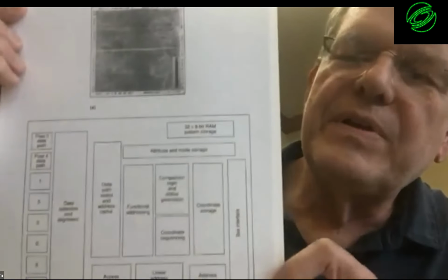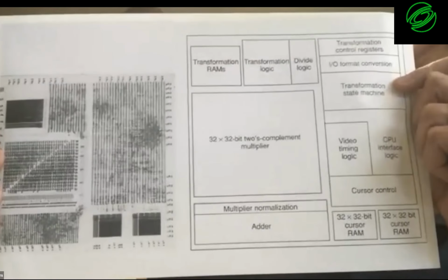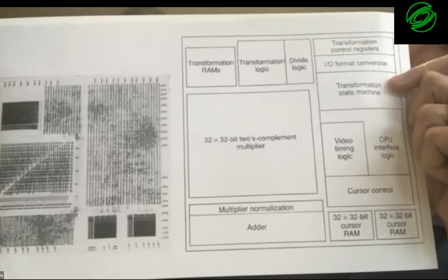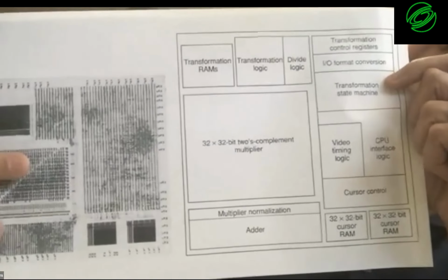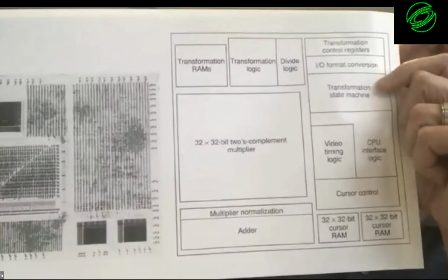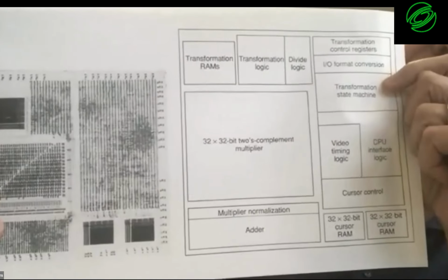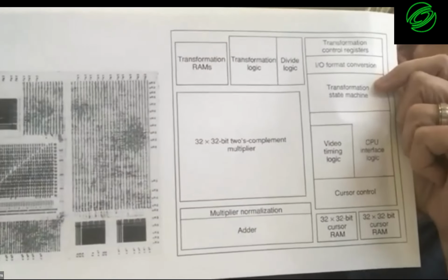One is sort of the layout of the FBC, to give you a feeling of all the different components, if you can see that. And this one is of the TEC, which was standard cell. The frame buffer controller was actually gate array. Because we had the multiplier, which is here, and then you had the cursor that you can see down at the bottom of the two arrays. And then you had the register array at the top, and next to it was the divide circuit. And then the rest of it was control and also the timing circuit.